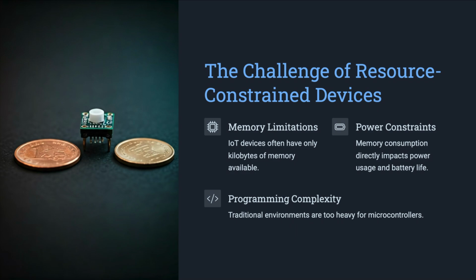They describe it as almost the opposite of 5G or 6G. Opposite how? Well, 5G is all about blazing speed, low latency, but maybe over shorter ranges. LPWA flips that. It's very low speed. We're talking maybe 1 kilobit per second. Wow, that's dial-up speed. Pretty much. But the upside is incredibly low power consumption and really long range, like 15 or 20 kilometers from one little module. Okay, so super slow, but it sips power and goes the distance.